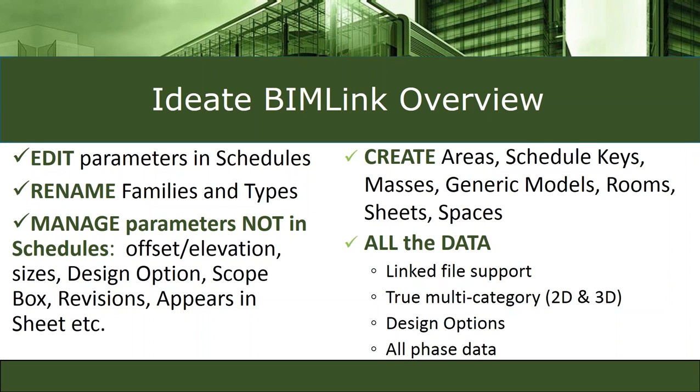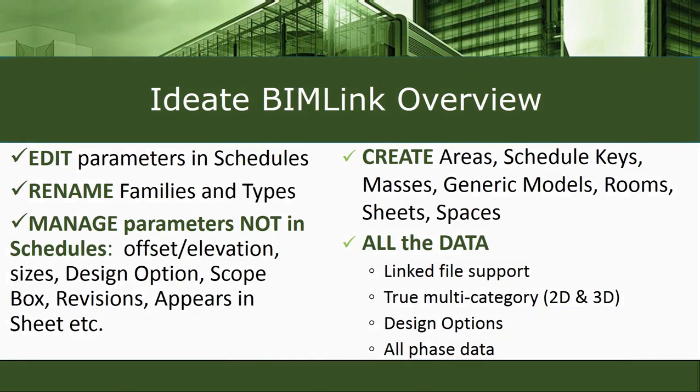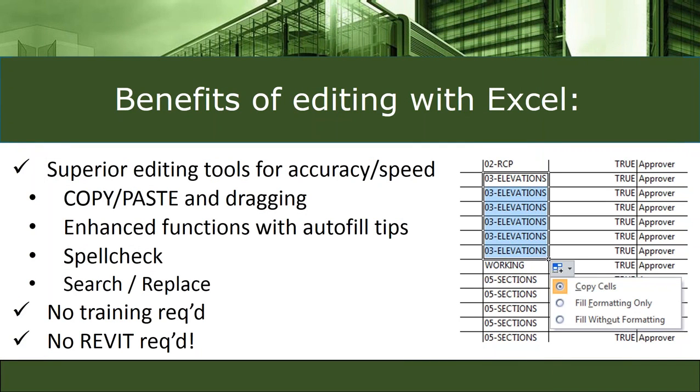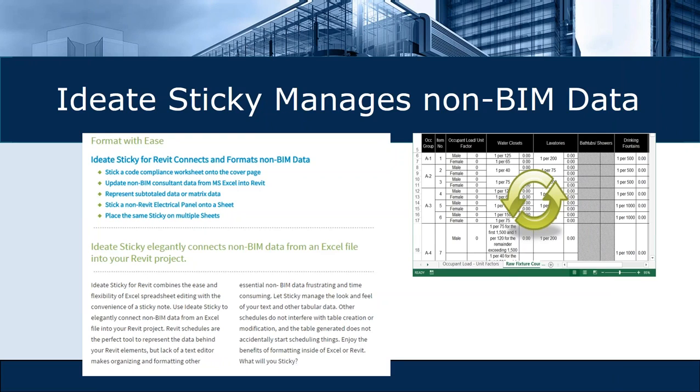Now, there are times where you don't necessarily want the Excel spreadsheet to drive the Revit model. You just need to be able to display maybe code information, design options, or design detail, or maybe general notes. You have this in an Excel file and you just want to display it within Revit. Well, that's what our next solution is for. It's called Ideate Sticky. Oops, I skipped one here, but Ideate Sticky is handling that non-BIM data, we're saying.